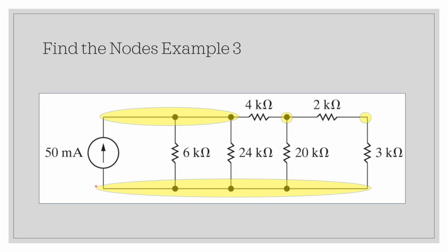Ohm's law gives us a relationship between voltage, current, and resistance at each of these nodes. So if we're looking for a current or voltage, we could potentially find it, but we may have multiple unknowns, multiple currents or multiple voltages that we need to find to solve the circuit. And as you know, to find n unknown quantities requires n simultaneous independent equations. So applying Ohm's law to circuit elements to find these unknown quantities could be helpful,